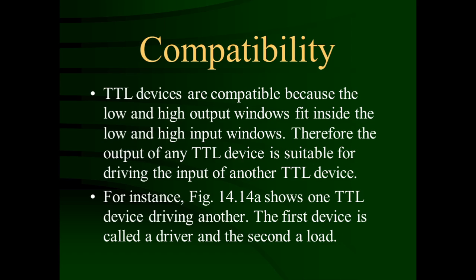That means, how can we check this compatibility? To check this compatibility, we have to see the TTL input and output profile windows. The output window of the TTL, that is from 0 to 0.4 volt, fits inside the TTL input window of 0 to 0.8 volt of low state.